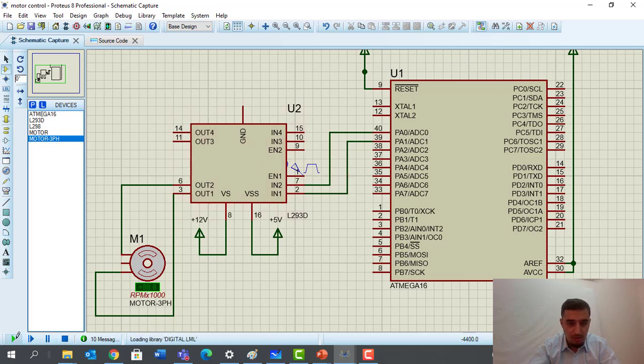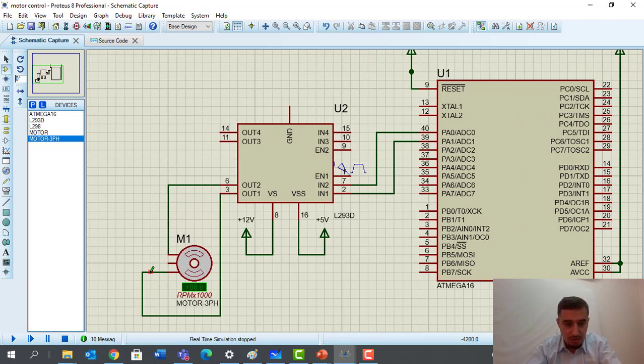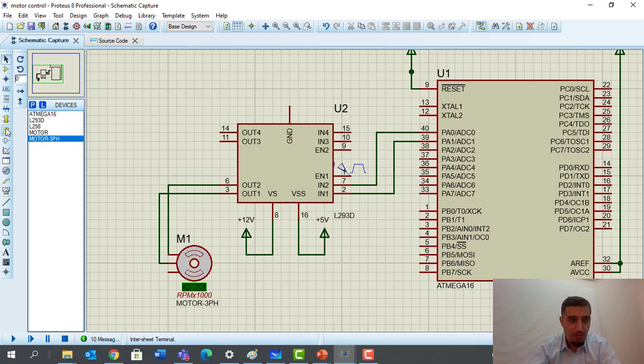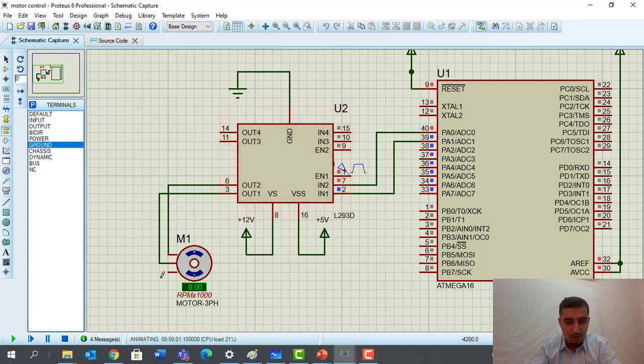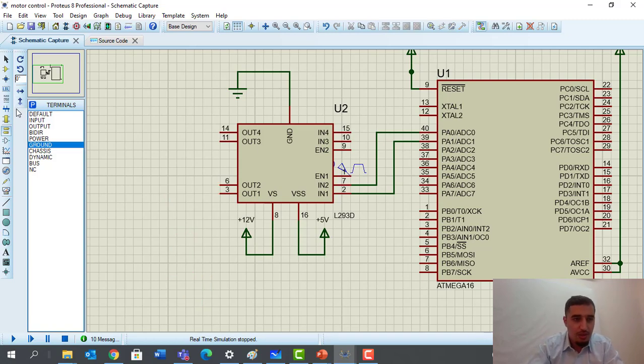Try to run. Okay, then it means that escape. That means we need to connect it to the middle one, I think, from here to here. Of course, I forgot to connect the ground here, so ground is important. Connect the ground. Try to run it once more. Okay, this motor is not the one that we want to use, so I can stop, remove it.